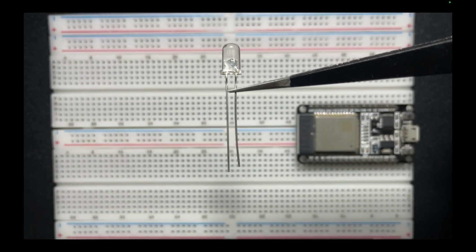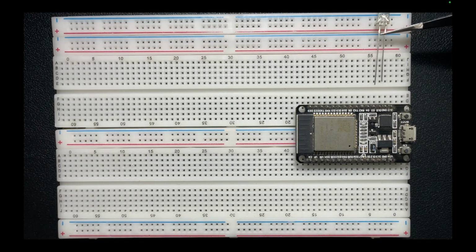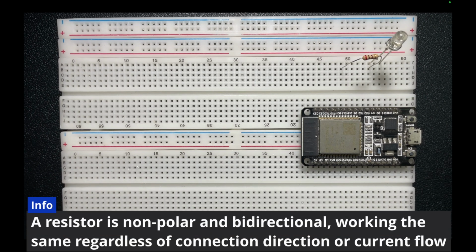Starting out, I want you to get your LED. I'm using a blue LED here. For the resistor, you can use a 220 ohm resistor. As we have not yet learned how to calculate the value for the resistor, you can go ahead with 220 ohms for now. Connect the LED across the rows like that and the resistor too, making sure that the long leg of the LED is connected to one of the ends of the resistor. The resistor is non-polar, so you can connect it either way.